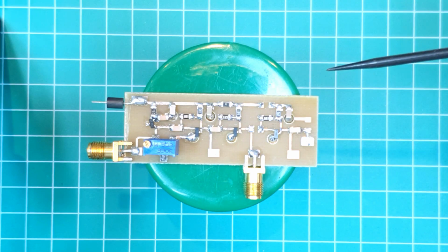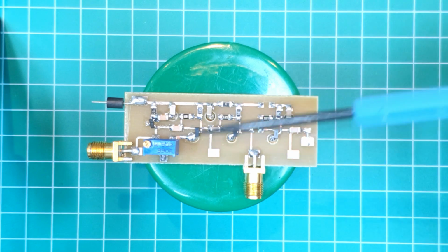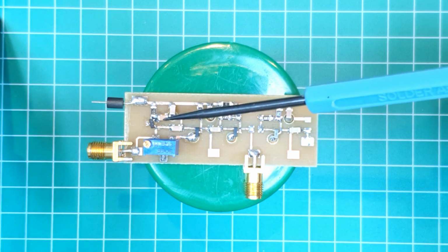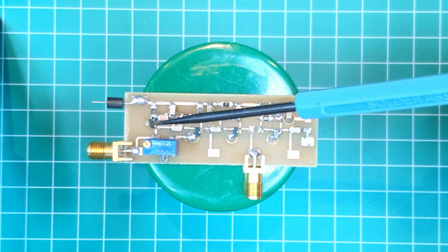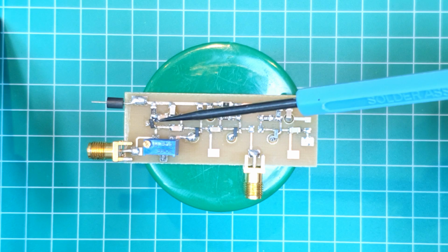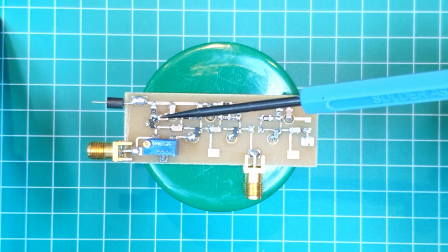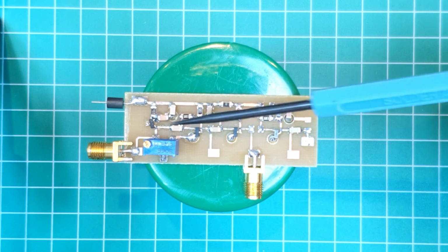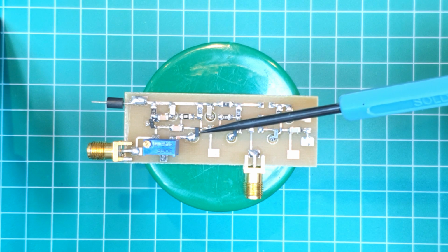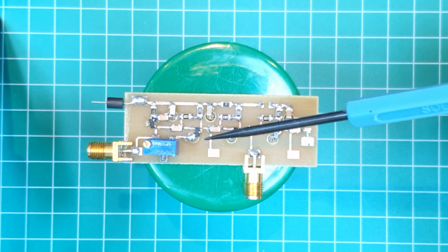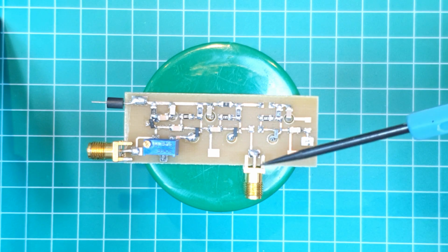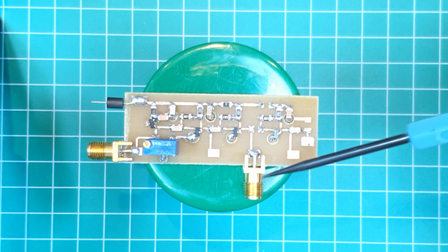This is the prototype that we're going to use in this video for experimentation. We see here that we have a power supply input, and we have a BJT transistor, which is actually our DUT, or device under test, where we have the base-emitter junction reverse biased. The trim pot controls the amount of reverse current in the base-emitter junction. We directly excite a first amplification stage, a common-emitter amplifier. The signal follows through the chain to the next amplifier, and this is the output, an SMA connector to be connected to the spectrum analyzer.